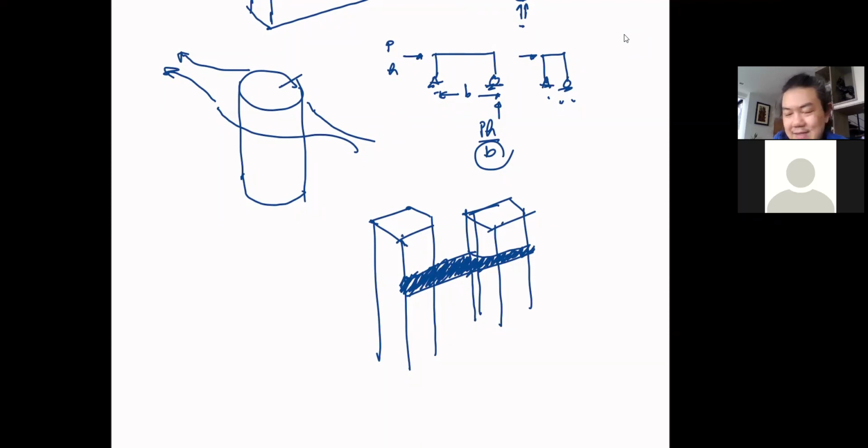For a case like this, there is no analysis available. You have to build the model and then put it in the wind tunnel to have the wind load analysis in the wind tunnel, because you cannot trust the software to be able to calculate complicated stuff like this.